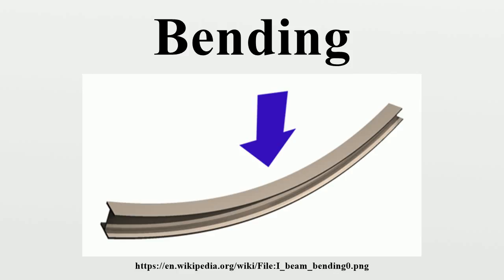Quasi-static bending of beams. A beam deforms and stresses develop inside it when a transverse load is applied on it. In the quasi-static case, the amount of bending, deflection and the stresses that develop are assumed not to change over time. In a horizontal beam supported at the ends and loaded downwards in the middle, the material at the overside of the beam is compressed while the material at the underside is stretched.